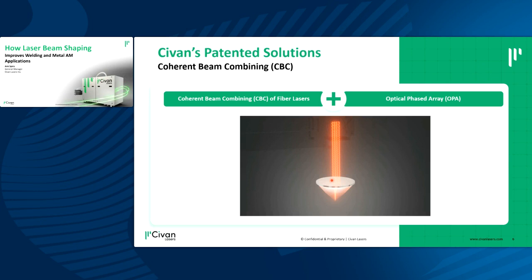But before that, when we combine all of these features together, what it gives us is the ability to control the thermal aspect of either welding or additive applications, and the dynamics of the molten material. With that, we can control the length of the melt pool, we can control the geometry of the keyhole, and we can tailor either the weld or the heat-affected zone that we receive in this process. And what is even more unique is that we can influence the solidification process, and everything that comes with that.